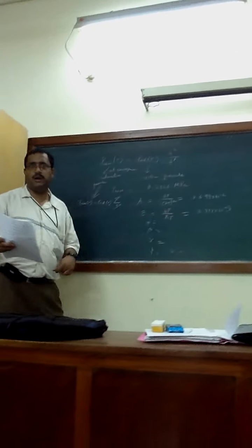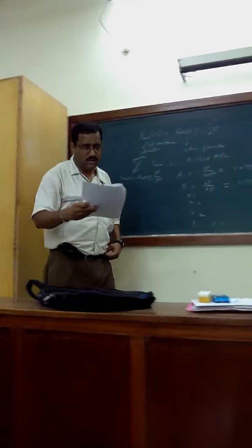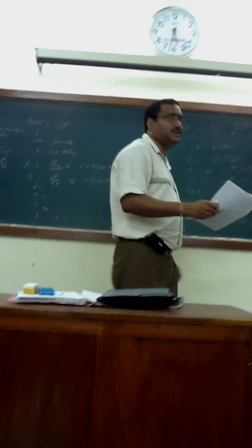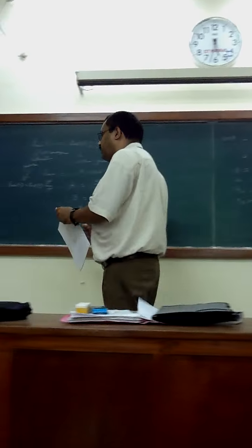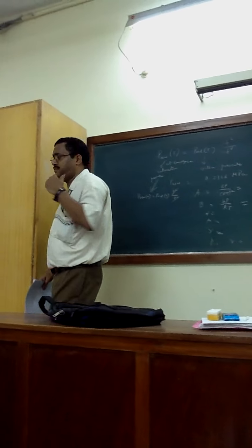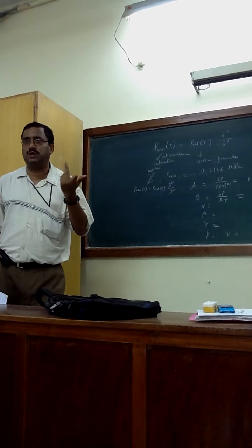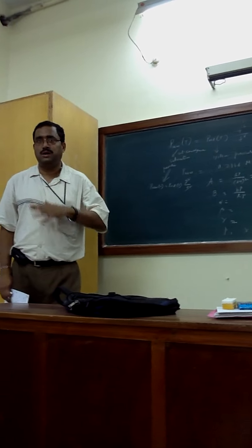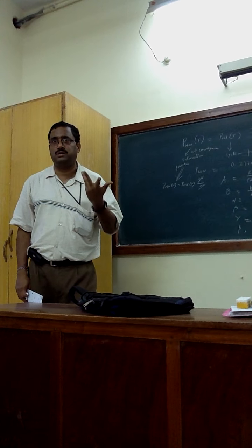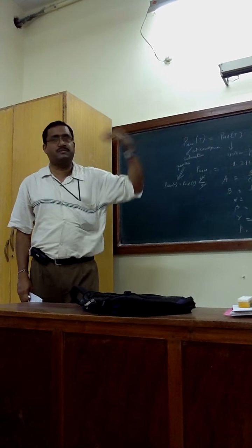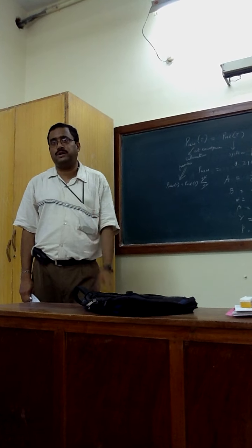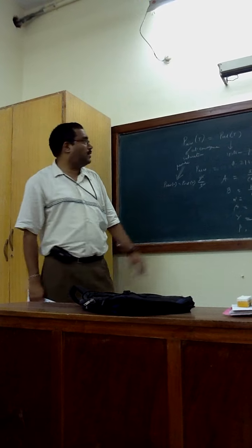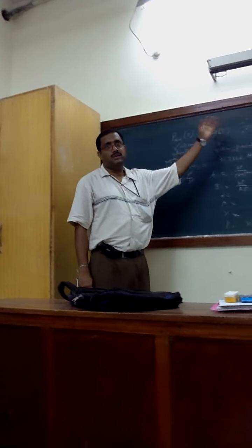You can do it at home, and next class I will ask you the answer. Then calculate Z1, Z2, Z3. Because here the D will be negative, less than 0, that means you have three solutions, Z1, Z2, Z3. From there you find out which is vapor and which is liquid. Then calculate phi L and phi V from the Peng-Robinson equation of state. Calculate fL, fV. And then you have the formula: if fL and fV are the same, then you got the answer.